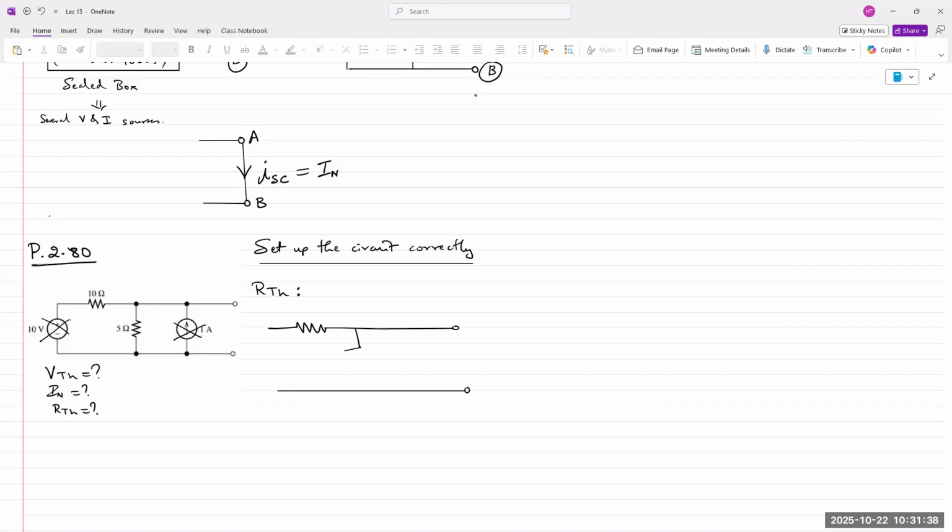And I have a resistor here. And I removed my sources from the circuit. Once I remove them, you have to replace them with something, okay? With voltage sources, if you remember superposition, what do we do with voltage sources? Does anybody remember? Sure. Well, we don't short the voltage source, we replace the voltage source with a short. And so we place a short circuit wire right here.